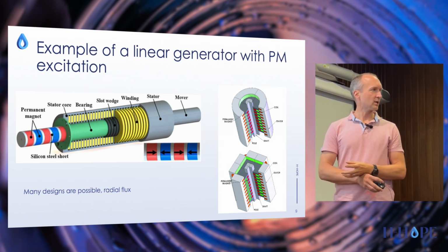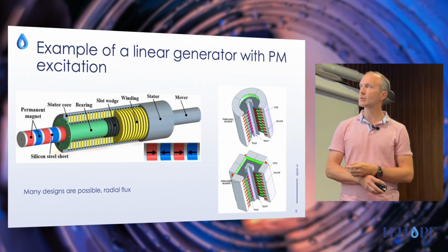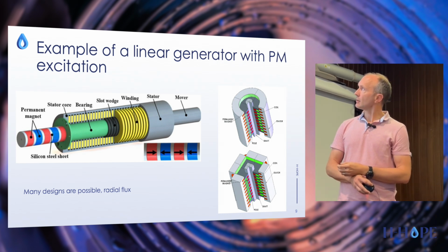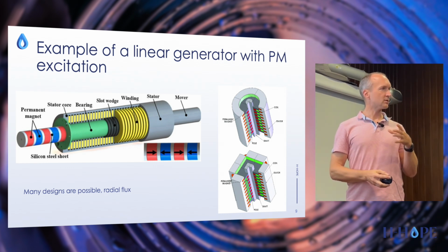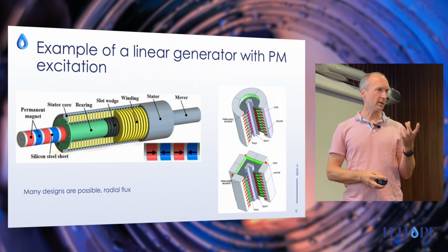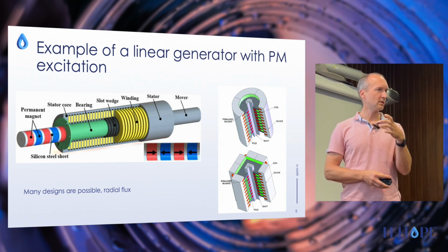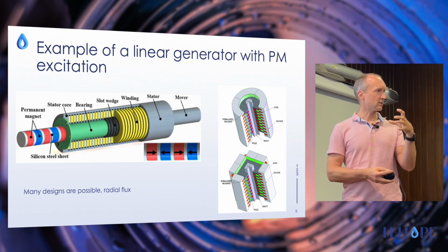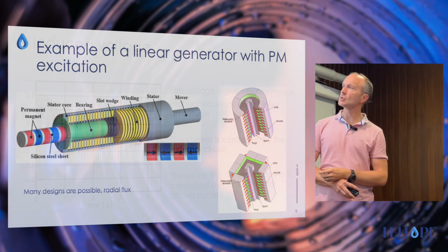So now we have to find different ways, the most effective ways, to put our coils in order to maximize the voltage and increase the efficiency. This tubular design is quite an effective way to get the coils inside with many turns, but also get the iron inside. The iron inside has the purpose of both stabilizing the coil and increasing the flux density. So iron inside the generator improves the efficiency. The drawback is that iron is attracted to the magnets. So you also have to make some mechanical structure that holds the rotor and stator, or the translator and the static part, with respect to each other.